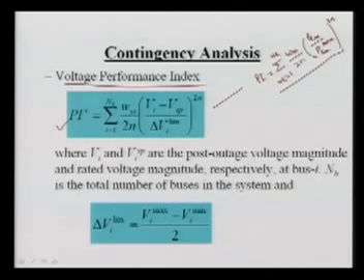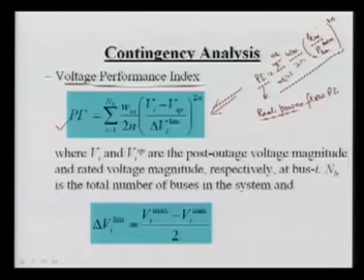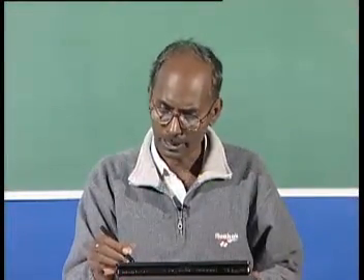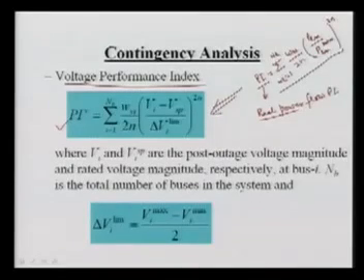You can see this is the power flow performance index, that is the real power flow PI. Why is it real power flow? Because we are taking the variable P_Lm, that is the power flow in particular line m, divided by the rating of that line, P_Lm maximum value, and then we are going for the 2n, where n is the exponent.